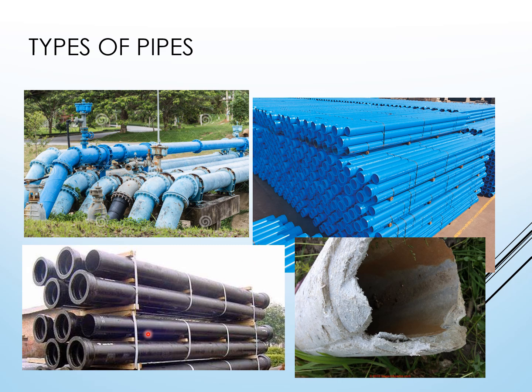You've got ductile iron pipes. Ductile is a great material. It's really strong, and not as corrosive, I guess, as cast iron pipe. And then you've got asbestos cement pipe, AC pipe. And this is that bad stuff that you're no longer allowed to use because of the friability of it and the cancer mesothelioma that's associated with it.